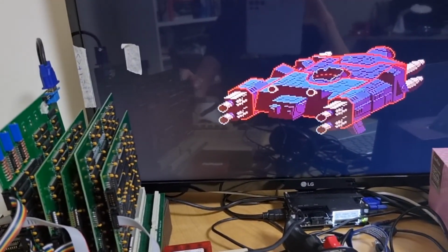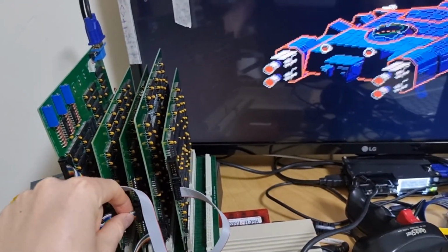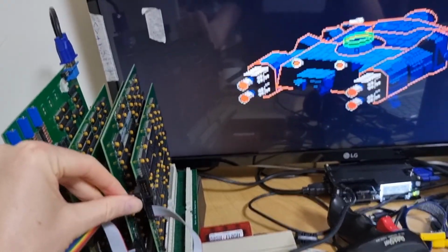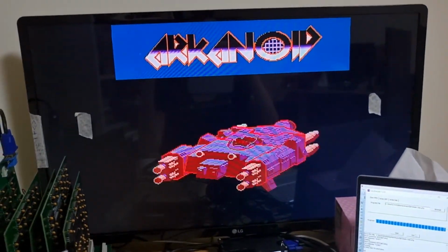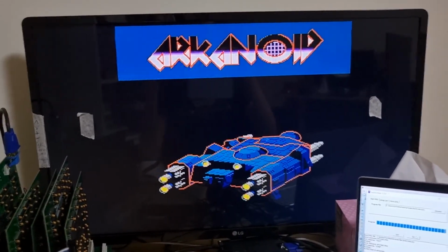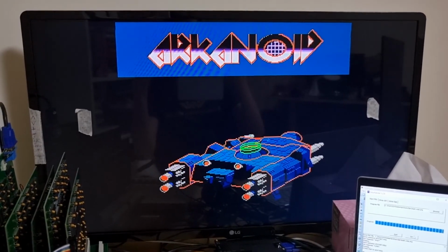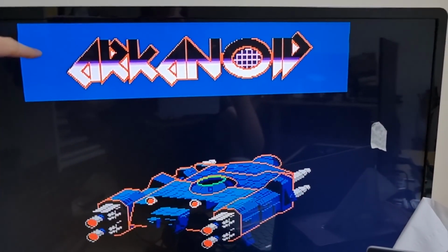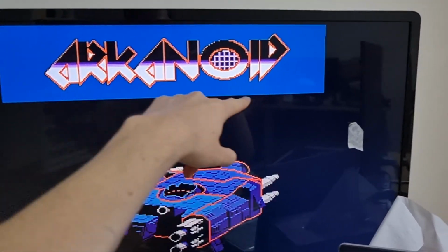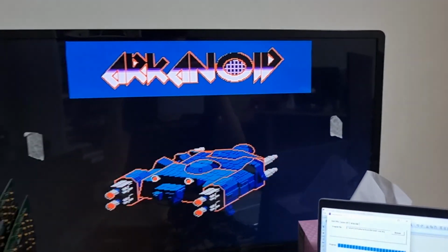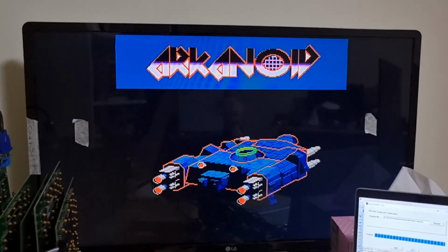What I should do is that the last character layer here actually should be connected to the tiles board output, and there we go. If I change it to be the same configuration as the emulation output, then the last layer on the tiles now is being used for the background color here. Actually, there's a raster split hidden behind some black colored characters here in the foreground. So also that works quite nicely.